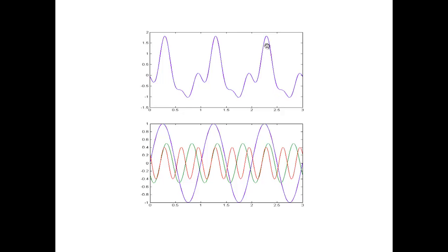But there's a nice way to look at these signals, better than just looking at them as a time series. Turns out that this one that I created is nothing more than 3 sinusoids of varying amplitude and phase added together. So here are the 3 down below. That's the dissection of this signal up above. The sum of these things is exactly this. But now this is a much easier way to do this. You see the blue here is the same frequency as the pitch. And you see that the red and green are higher frequencies. In fact, they are multiples.